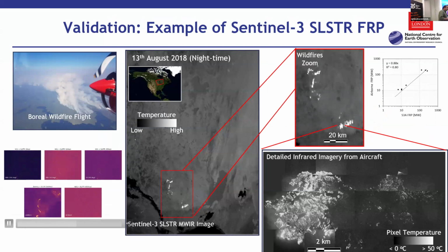because you saw in the first picture, early on in the graph, that in the middle infrared, the radiance goes up hugely in a non-linear way with temperature. You can't get a middle infrared camera that can measure from 0 to 1,000 Celsius, for example, as you might need.